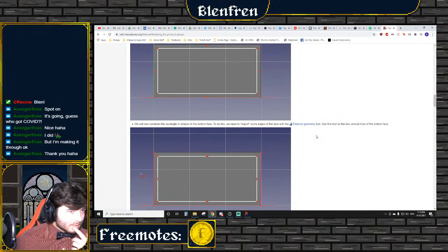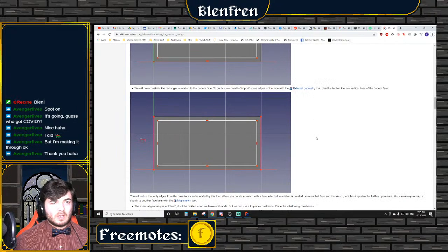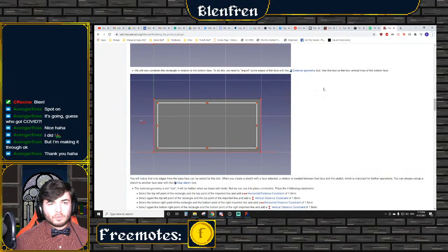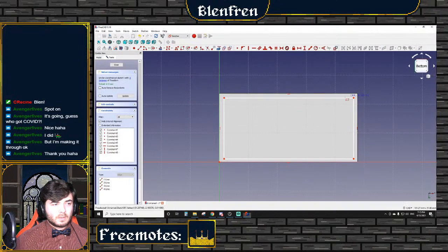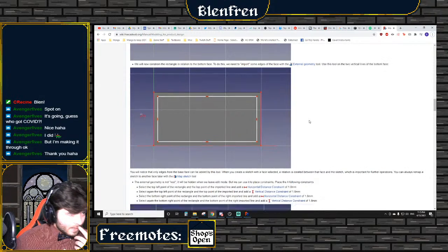We will now constrain the rectangle in relation to the bottom face. We need to import some edges of the face using the external geometry tool. Use this tool on the 2 vertical lines of the bottom face. Nice. So I think what we need to... This is it. So I think there we go. And then...